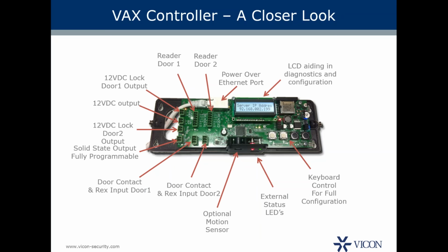12 volt, 500 milliamp is the power that we'll run. So that's available at the door. Supports both electronic strikes or mag locks through the PoE. We have support for in-out reader configuration. We have 4 digital inputs that are fully configurable as well. The image here shows the common user case, but it can be a combination, any that you want. 4 contacts to 1 door or 2 doors per. So there's a different variety of ways that you can do it. Again, a lot of versatility at the door, over the door, or back in the closet.